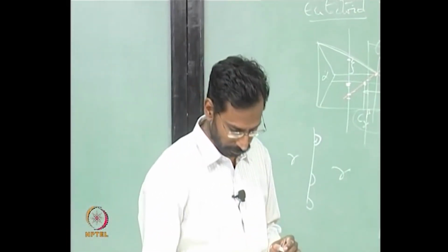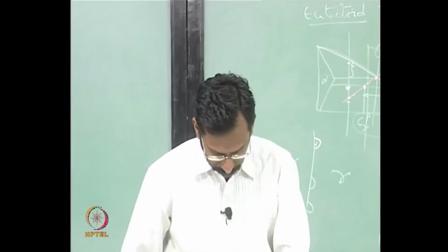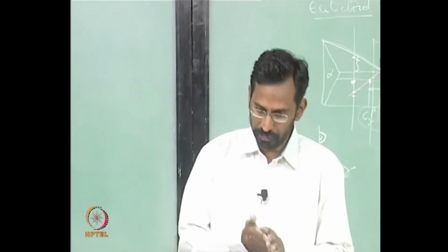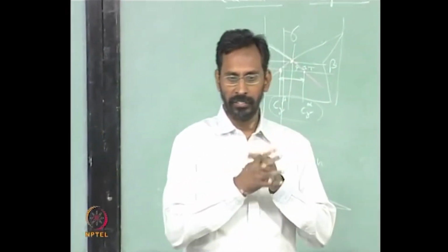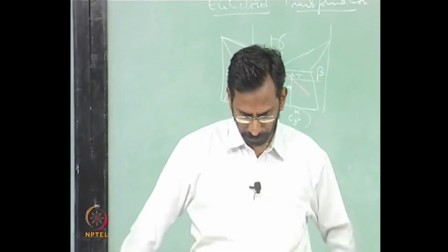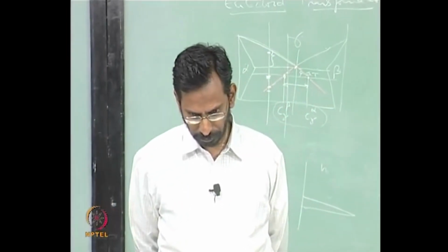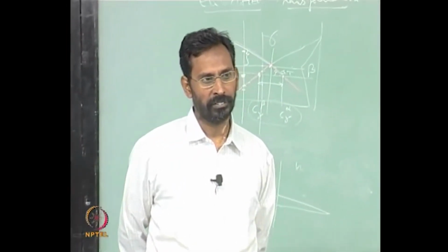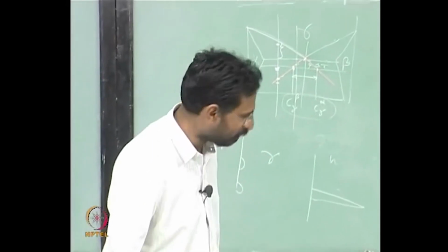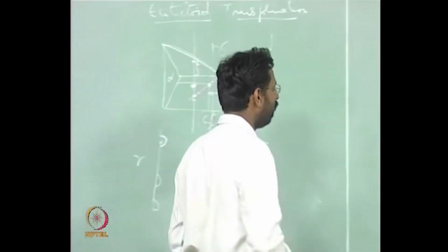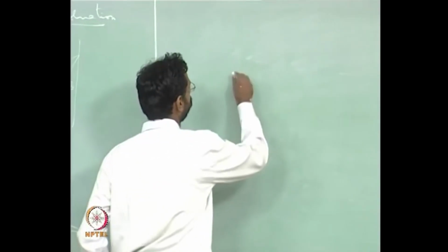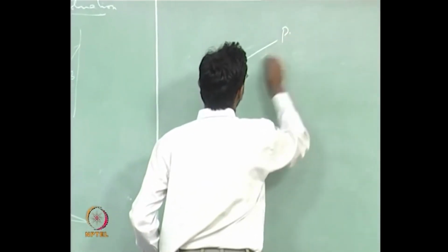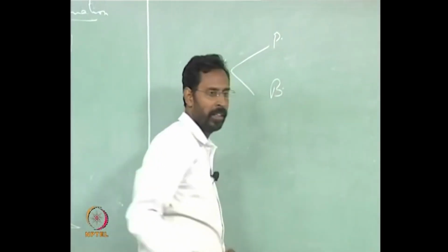In bainite formation, the ferrite is the active nucleus. And in the eutectoid, it is the ferrite formation, then the cementite. Why is there a difference? Again it is not very difficult to understand. See, if you look at the two transformations, gamma giving pearlite, gamma giving bainite.